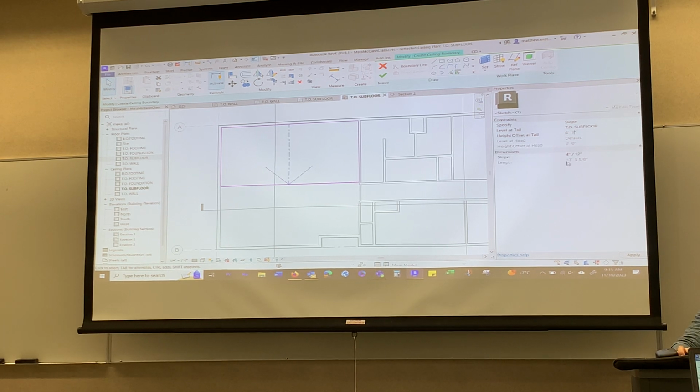It's no big deal. Now the inside slope obviously, we have scissor trusses, right? So they're gonna be thicker at the top, come down to the heel. So I don't think the information's on the DWG, so 3.5, usually where that's gonna be, maybe 2. It's not gonna get more than 3 because I don't think they can design the truss to span quite that far. They have in the past, and it was a 2x6 top and bottom chord. So I got them to change it so that the trusses were lighter. Because they're scissor trusses and they're a little bit dangerous with students that have never touched a piece of wood before, so they wanted them as light as possible. So, remember this is the house we used to build.